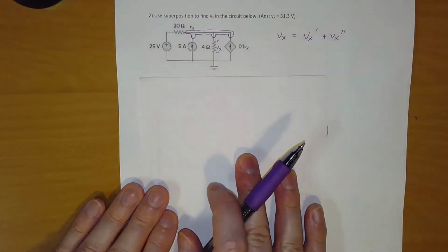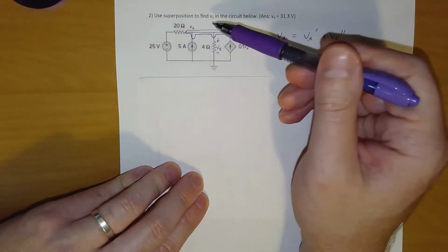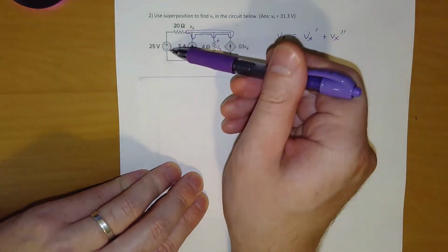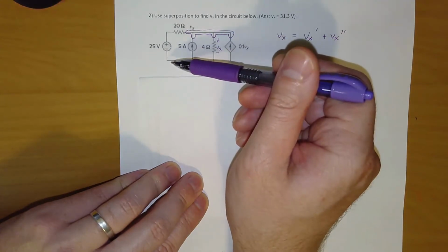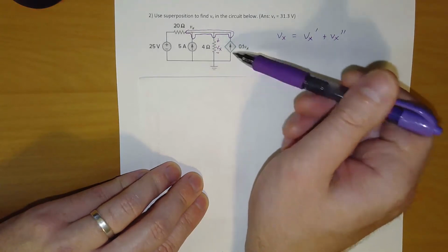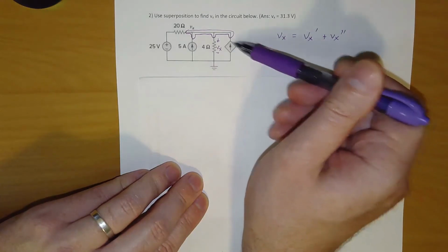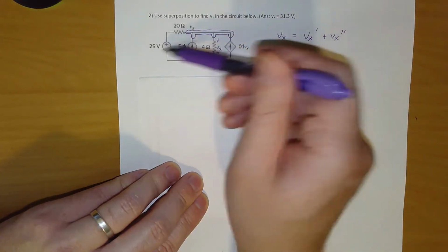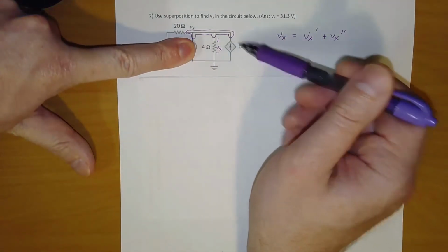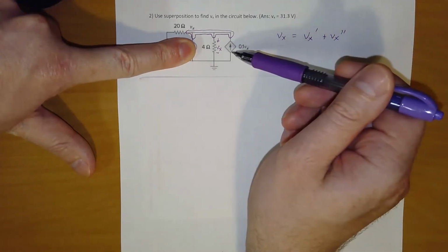It's fine. So what we want to do when we're solving one of these problems is pick an independent source. So I'm going to start with the 25 volts, and we want to redraw it with every other independent source turned off. So notice I'm saying independent source. We're going to leave the dependent sources on because what they do depends on the independent sources. So they don't do anything by themselves. If I turned off both of these things and this was the only thing on the circuit, you'd find that it doesn't do anything. All this is going to do is modify currents and voltages.